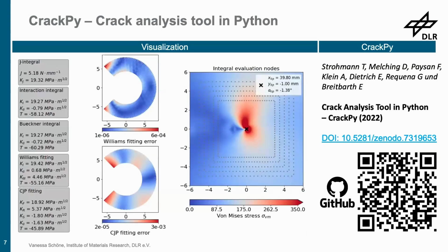And afterwards, we can, for example, calculate the stress intensity factors using the J integral or the interaction integral. So just try it out. And this is the method that we use to determine the stress intensity factors in the numerical and experimental setup.